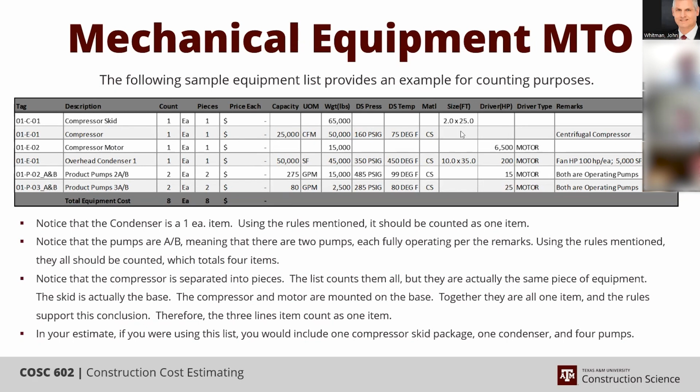But if you're doing it properly, you'll go, okay, we've got a compressor, it's centrifugal. The picture I showed you was reciprocating. This is a different compressor. It's centrifugal, it's 6,500 horsepower. Okay, my charts say that's going to be 1,500 hours to install.